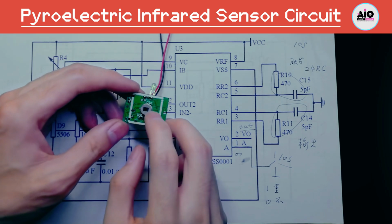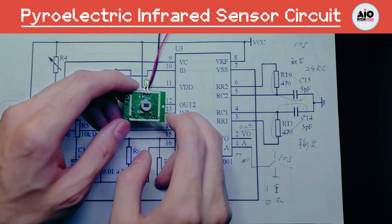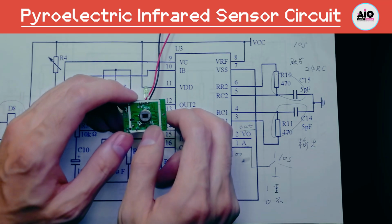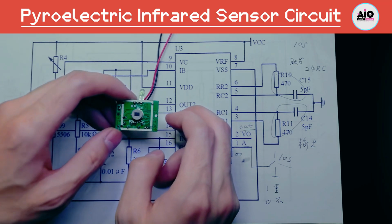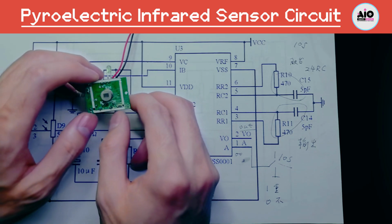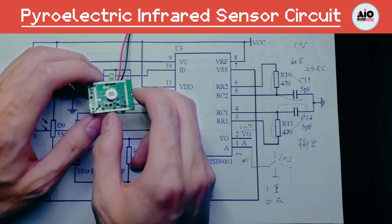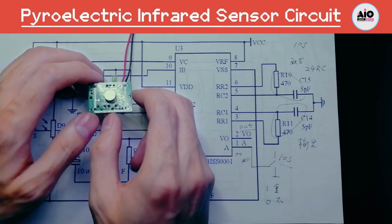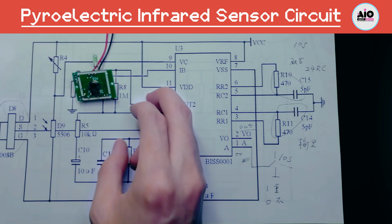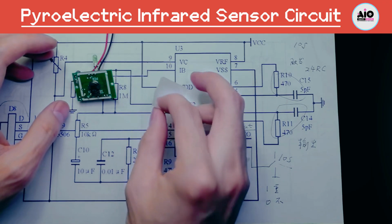There are two pads here. The two pads are to control the repeated triggering. The window in front of the infrared sensor is just a light filter. It does not have the function of condensing light, so the angle of the incoming light becomes larger, the radiation range it receives is larger, and its sensitivity will decrease. So a lens will be added in front of it to process the incident infrared light.